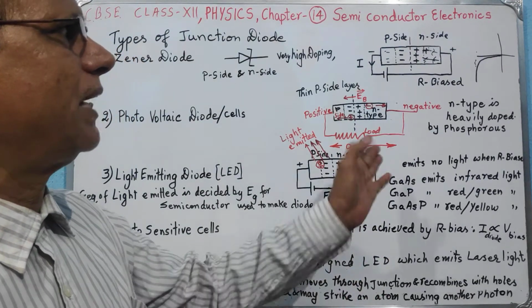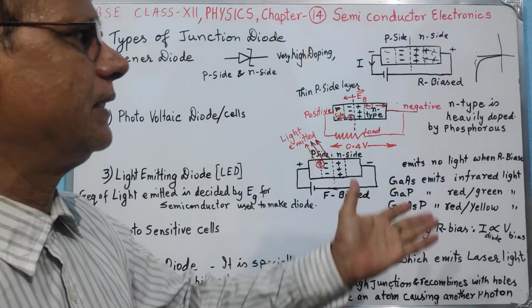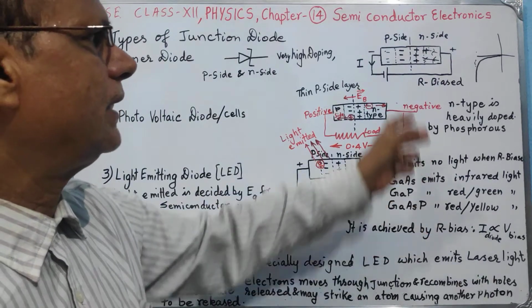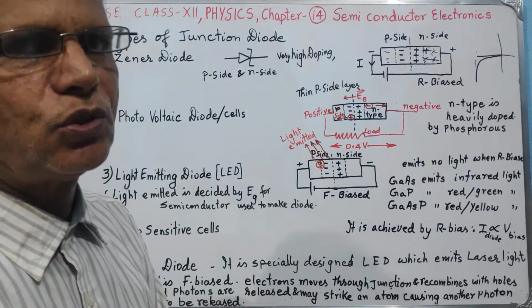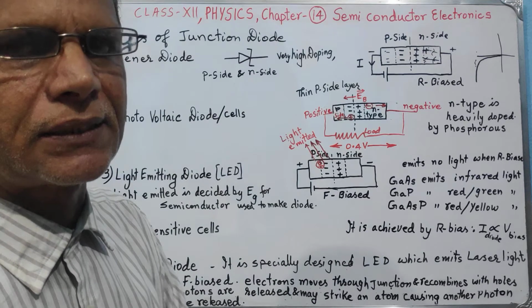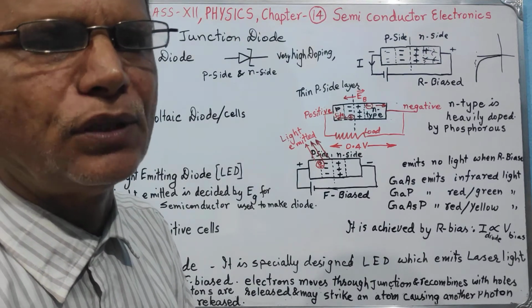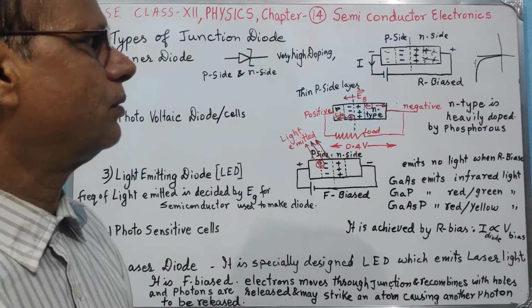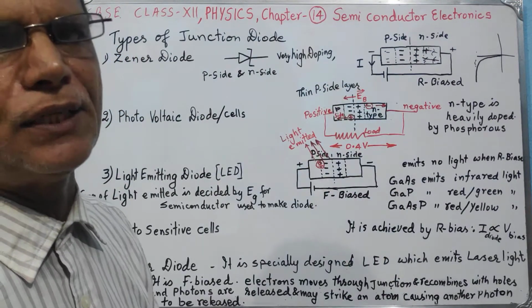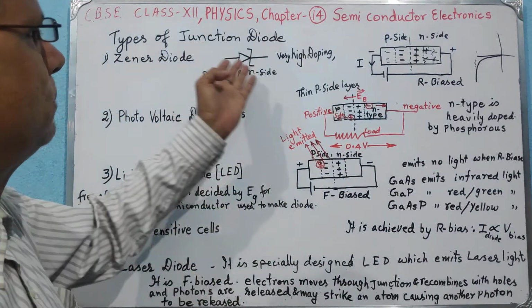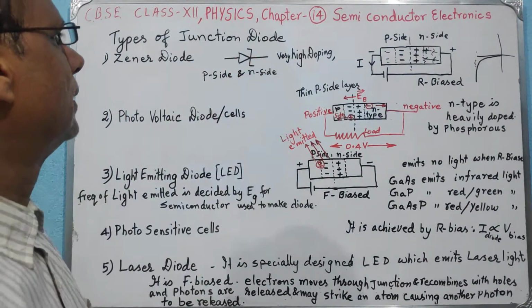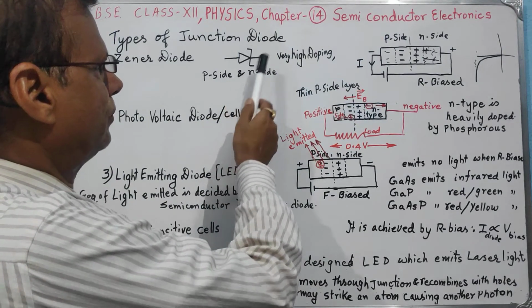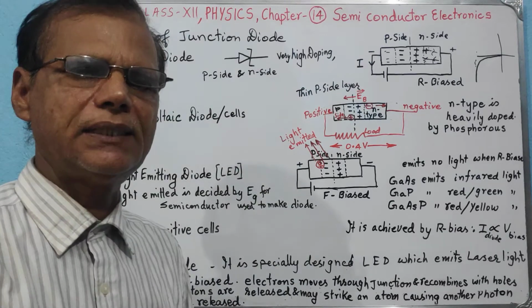The moment the supply voltage becomes greater than the Zener breakdown voltage, the current drawn by the diode becomes very high, so it virtually checks the rise in voltage, and therefore it protects the device from the high voltage given to it. The symbol for Zener diode is just simply modified by giving a Z sign over here to indicate that this is a Zener diode.